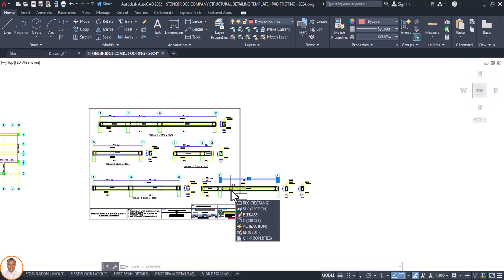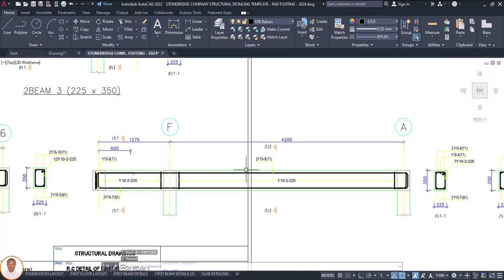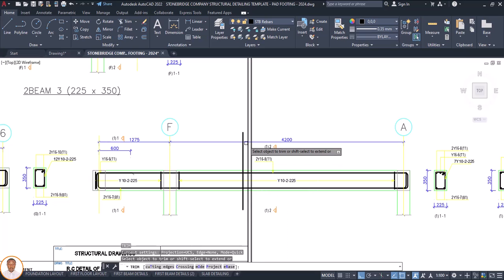Because if I do not explode this, I will not be able to cut it. Is that okay? Or trim it. So explode, then enter. Once I've done that, I pick my line. Enter. Then F8 to make the line straight. From here I can just click like this, escape, then TR, which stands for trim. Enter. Then zoom in.